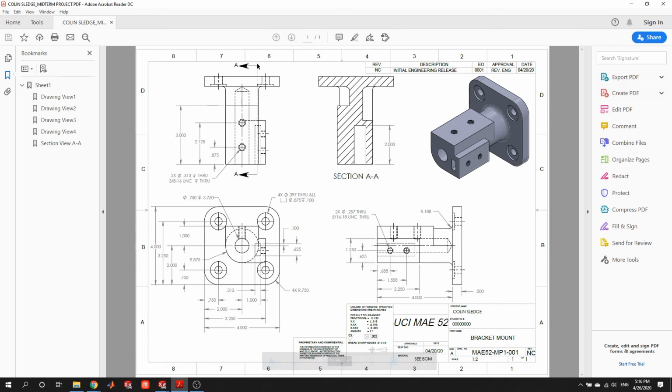And if you look at how this is aligned, it's aligned basically to the edge of the counterbore. So while the important part is to make sure this pocket is clear, we don't want any other features that are only showing partially cut, because it's a little bit distracting. So we're going to be careful to align this cutting line so that it doesn't cut through any other information that we don't need. We really want to highlight the depth of this pocket.